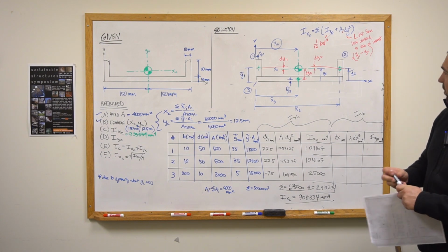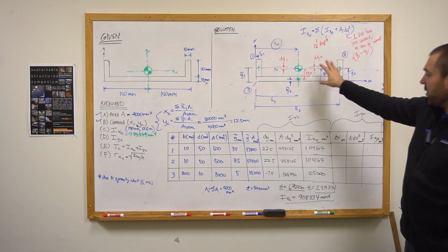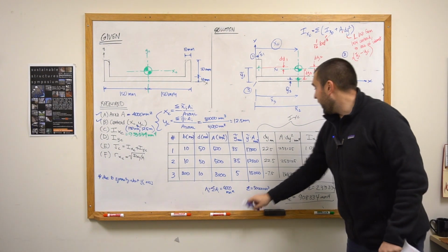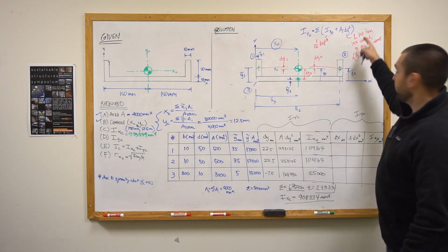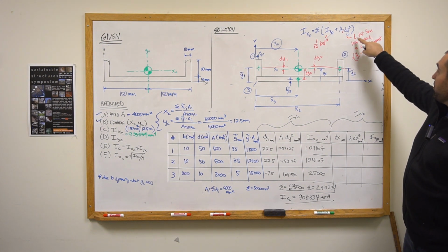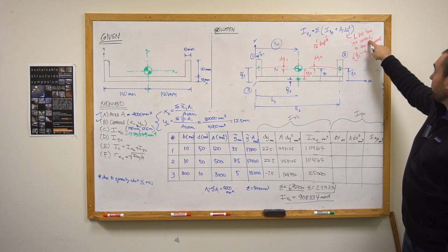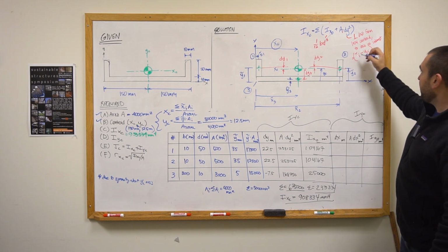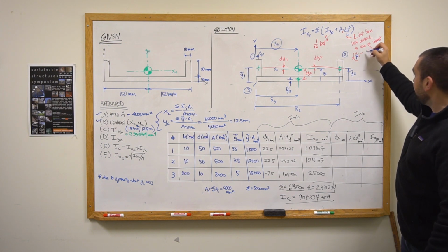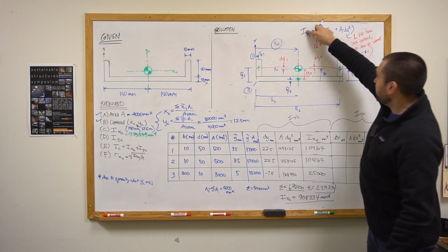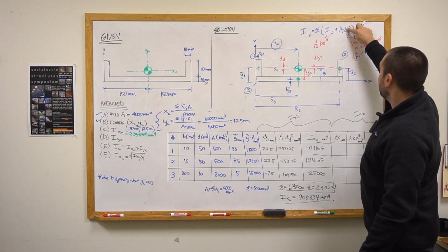Now, what we need to do is show on our plot up here what that dx value looks like, and that's defined the same way. It's going to be the perpendicular distance from the local centroid to the axis of interest. And I'm just going to change these values to xi minus xc.